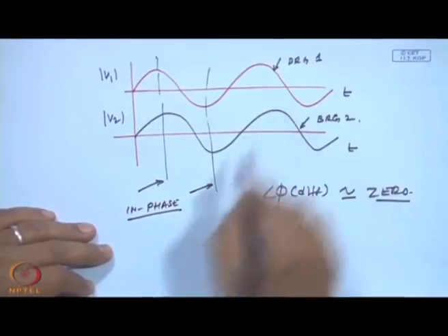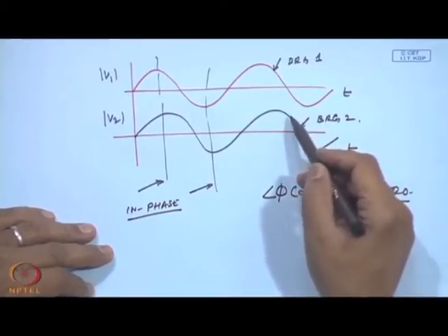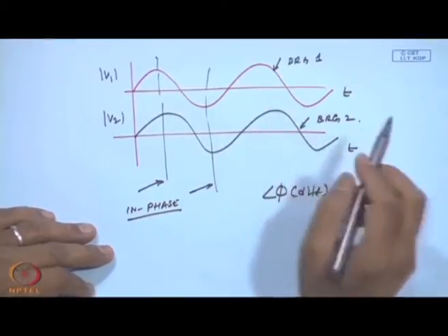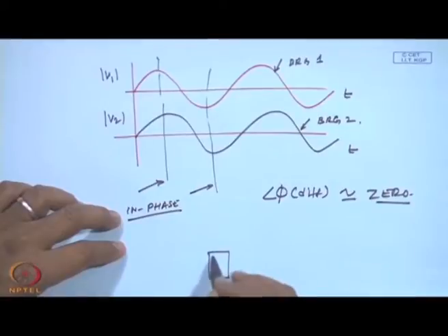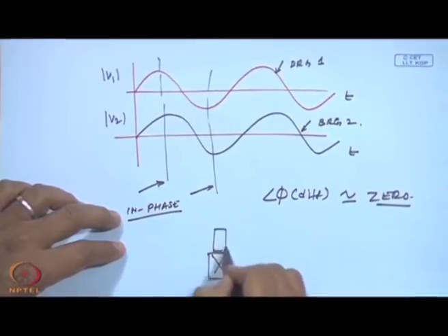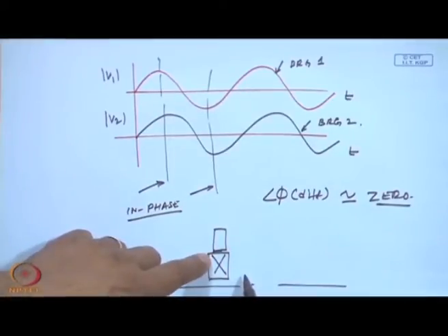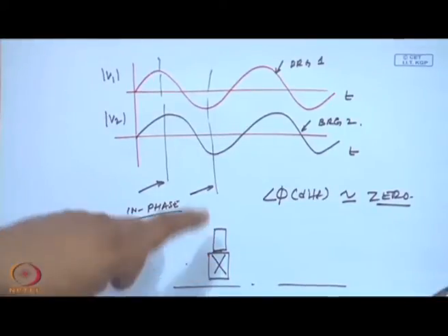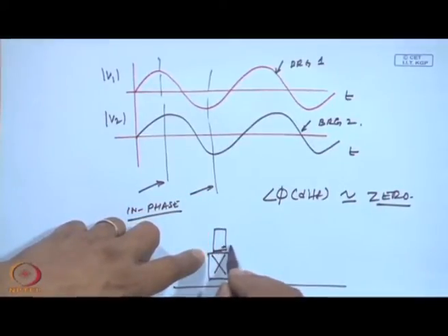When I drew a sinusoidal, if I show you an unbalanced time history of a signal, this is nowhere close to this, because in a machine everything is mixed up. This sensor which we put on the bearing measures a lot of things. It measures the bearing vibrations on top of the unbalances. Suppose the shaft had some other problem, like things were loose, the shaft had a crack, or the shafts were misaligned. All these vibration signals are going to come into this accelerometer here.